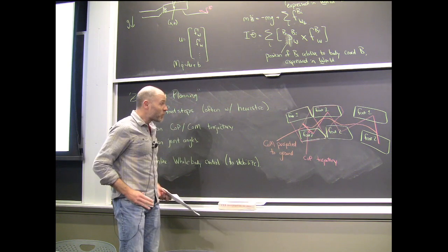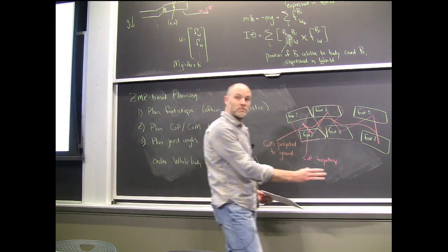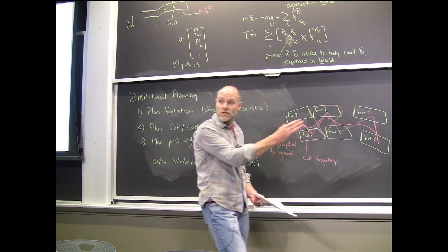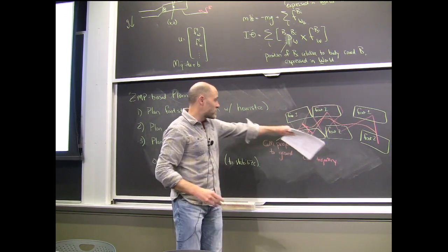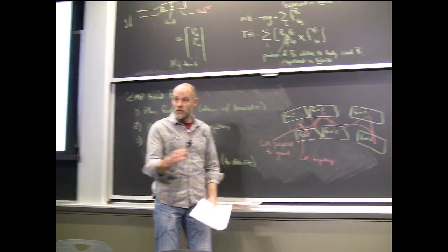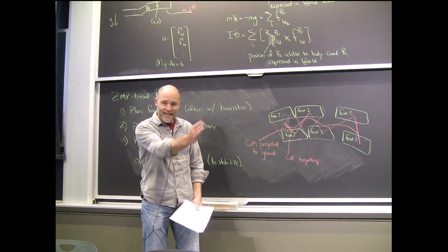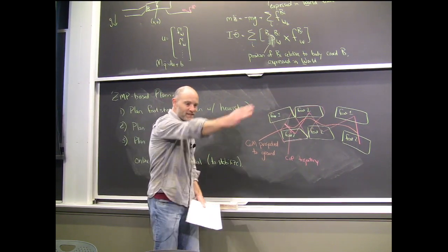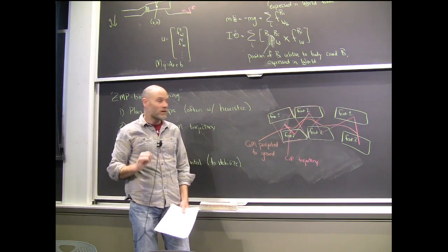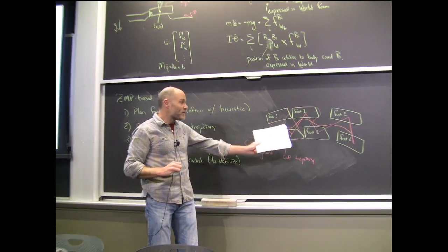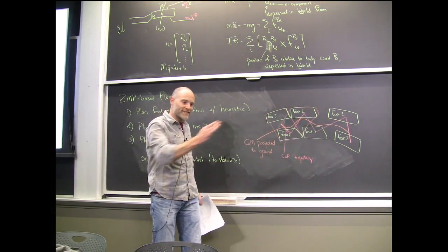Okay, but when you're moving fast, your center of mass is almost completely straight, and very small deviations of your center of mass can have large effects on your ZMP, and you can stay stable. And it's actually easier to execute something where your center of mass isn't swinging back and forth. So we found very much that walking gets easier as you walk faster.